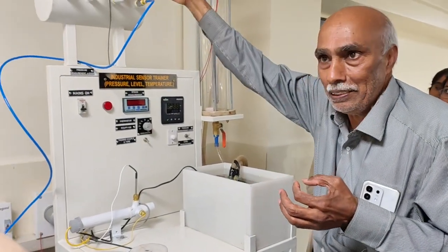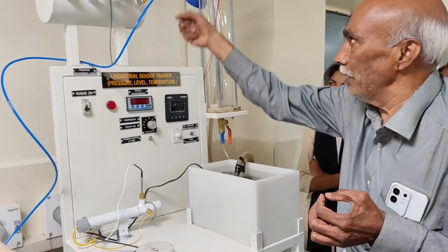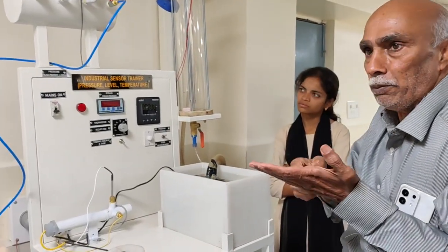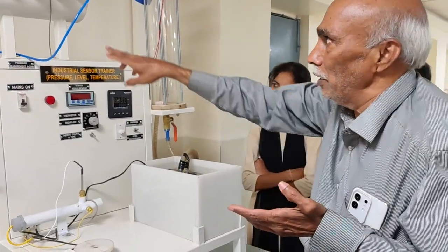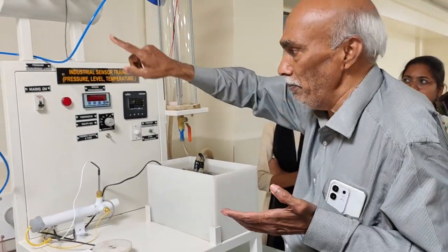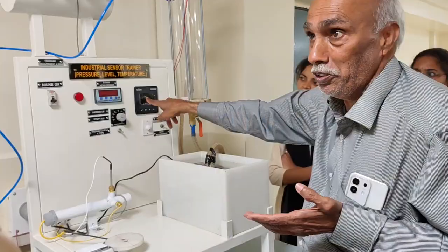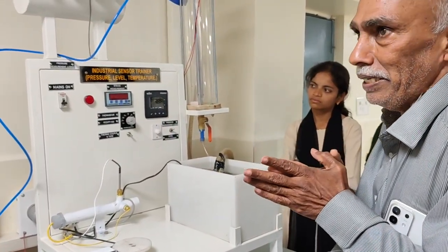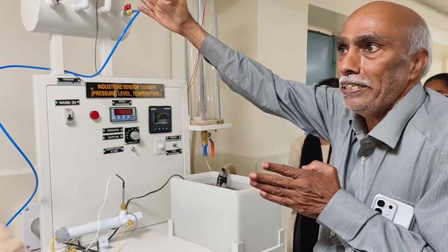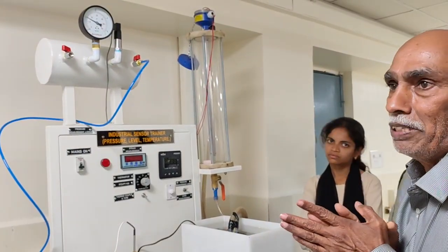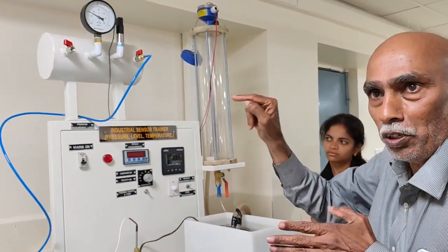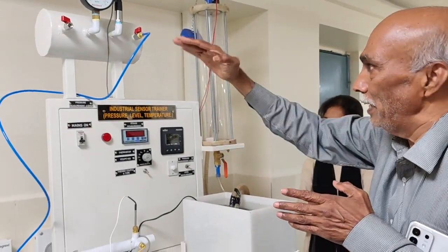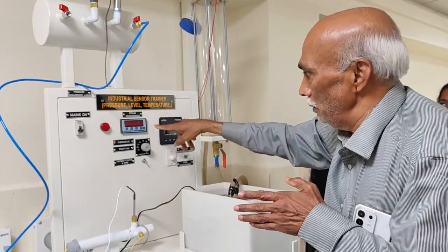When you give an excitation voltage to this, from the electronic device, some voltage will be given to this. The coil gets excited. It starts producing 4 milliamps because the pressure is zero here. At 4 milliamps, you need to read, that is how you need to learn the scaling of this. We call it scaling. Scaling means according to the unit. What is the pressure unit? Kg per centimeter square. At 4 milliamps, you are supposed to read 0 kg per centimeter square here. At 4 milliamps, when there is no pressure, the pressure gauge is 0. 4 is the minimum.